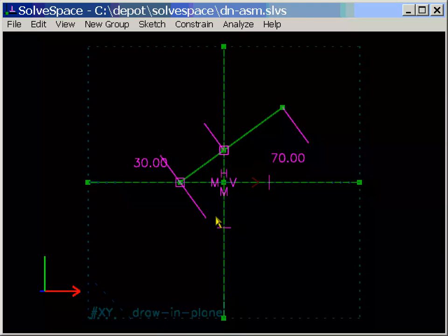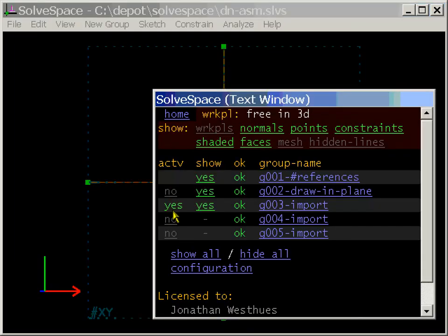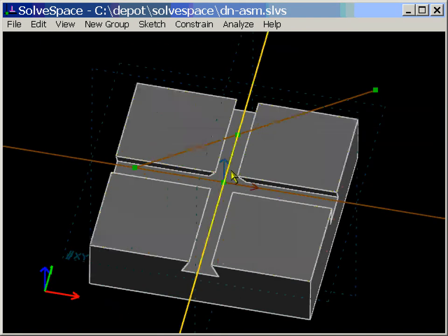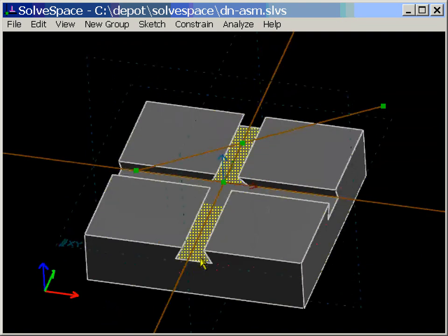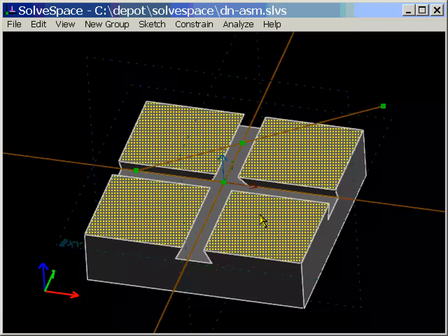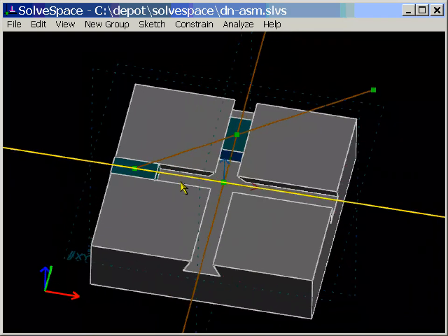We can combine mechanism design with solid modeling. So here I've begun by drawing the backbone of the mechanism. If I wanted to implement it for real, then I might represent these two tracks, for example, as a block with a couple of dovetail slots. And I've drawn that here. So this is an assembly. We've imported the part that I drew here with the two dovetail slots. Then we might import a couple of dovetail slides that fit in the slots. And we can see those here too.